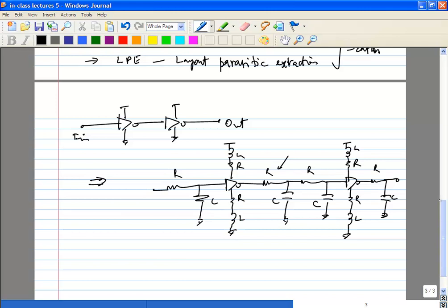Okay, if you add a large inductance, which is definitely going to exist in real life, in the supply or ground paths and try to simulate it, you will see all kinds of weird stuff going on. That itself will tell you that inductance is very important. So you can do one more level, which is inductance extraction.